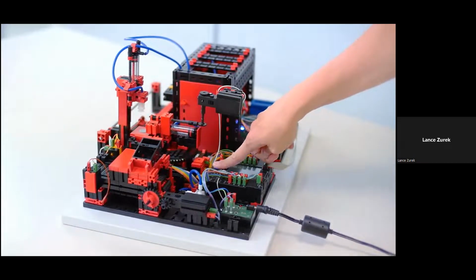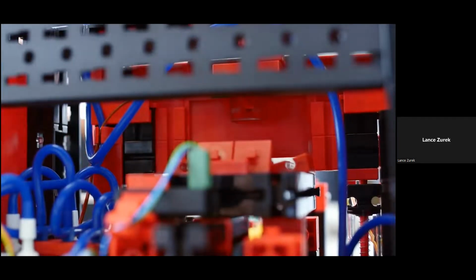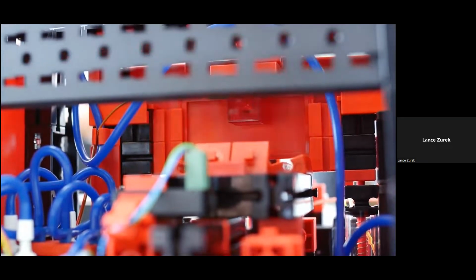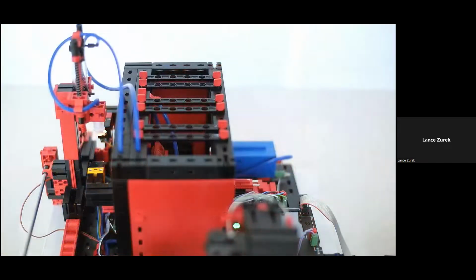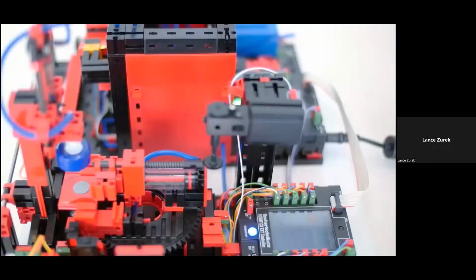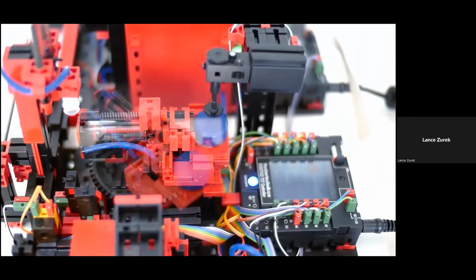The dimensions for the model are approximately 20 by 14 by 12 inches, and it has a weight of just about 11 pounds. Again, the standard version of the model is the 24-volt version for use with the PLC of your choice, with once again a relay board for motor polarity reversal and both the multi-pin connector, 34 pins with a grid of 2.54 millimeters, as well as additional PCB terminals with push-in connections for all inputs and outputs.